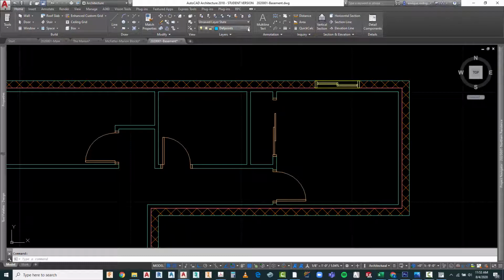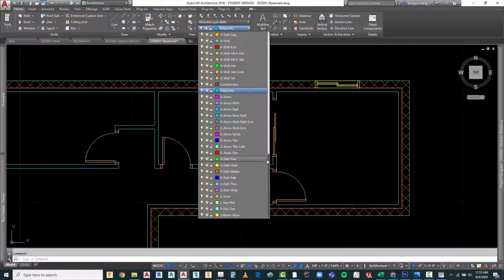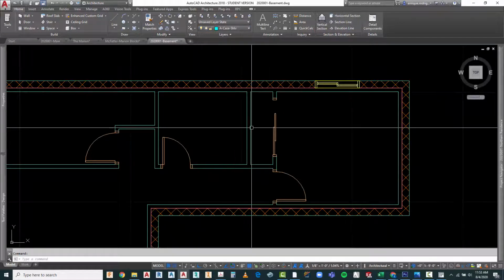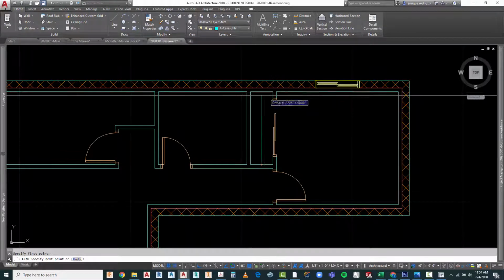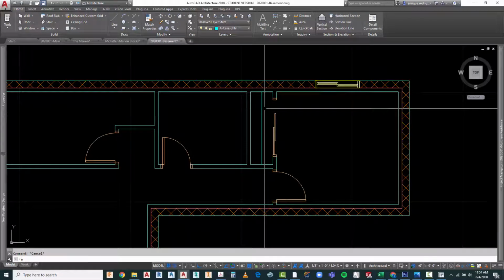All right, so let's go to our layers. Click on that to open it up. And it's either going to be in the A shelving above, or we also did it in terms of the casework. So there we have A case shelving, which is what we want, and we have, let me see if we've got the other one located. So let's start with that one. Line. Right up there. Remove it about 2 inches out.